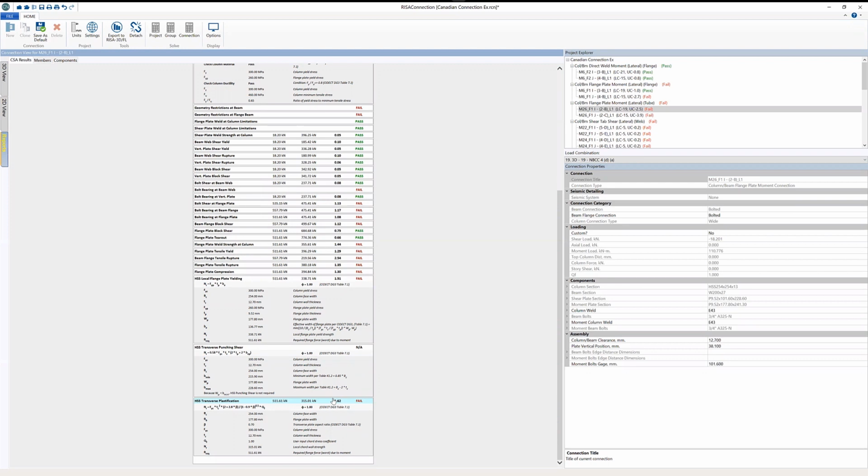Now, one thing I want to mention before we go ahead and send information back into RISA 3D or create reports, one of the things you can do here is what's called detach, right? What we've been doing this entire time has been looking at the connection of RISA 3D, RISAFloor to RISAConnection, right? So this kind of connected approach, this kind of one model approach, where the information based on the loads, the load combination, and then here the shear and moments, all this information is kind of grayed out because it's coming from the larger model.